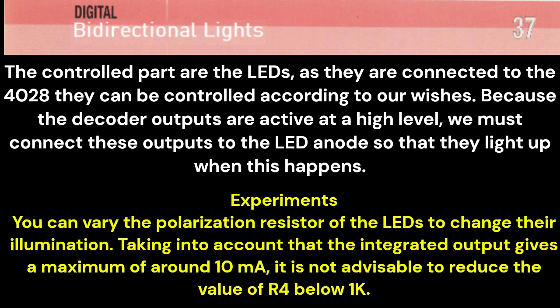Experiments. You can vary the polarization resistor of the LEDs to change their illumination. Taking into account that the integrated output gives a maximum of around 10 mA, it is not advisable to reduce the value of our resistors below 1K.